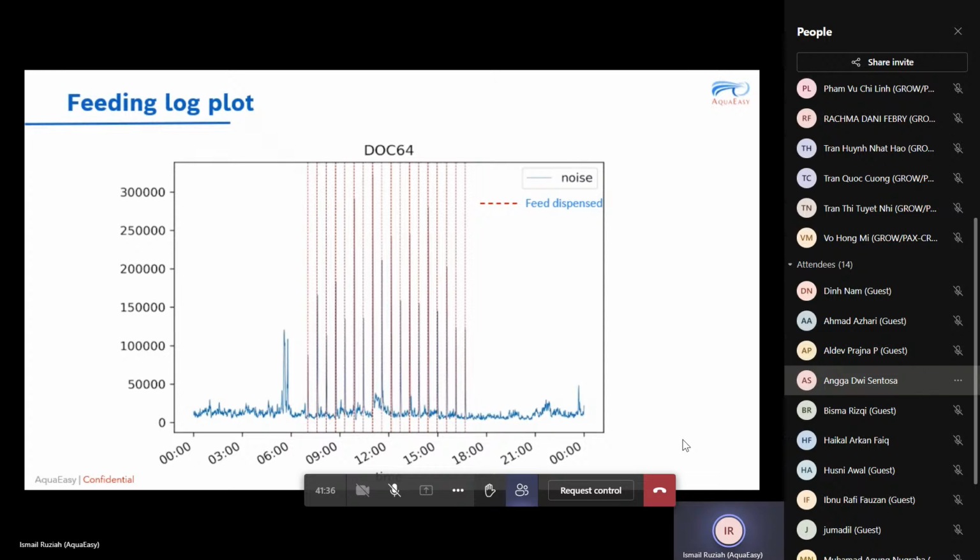The other setting here is the auto wiper, I think. This triggers one round of the physical sensor cleaning, and it's used to clean the physical sensor. If the DO is low, I suspect it's because the physical sensor has algae or something blocking it. You can go into this tab, click auto wiping, click multiple times to trigger it, and you see the DO reading improves. So that's the advanced tab.